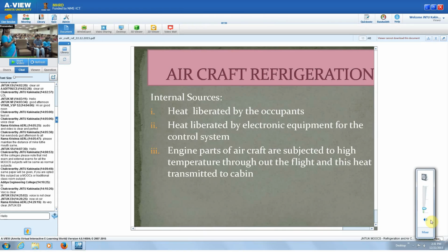You know that the movement of the aircraft depends upon the gas turbine. Here, jet propulsion you have studied in thermal engineering too. In that you have seen that the engine works only due to two laws, that is Newton's second law and third law, which requires a gas turbine and also a nozzle. In the gas turbine it requires a compressor, then a combustion chamber, and then a turbine.